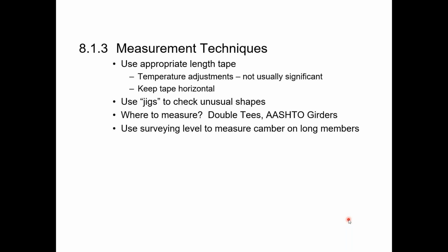Every now and then, I guess wrong, and I try to measure where I think it might be, and I get back and look at drawings, and it's not exactly the same. We're not really comparing apples to apples, and I have to go do it again. But there's things you can do. Make sure you understand how you typically display information on your plant drawings, so you know where to measure.